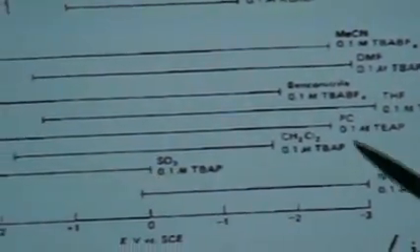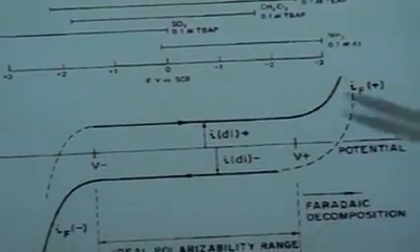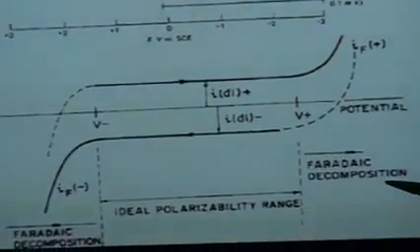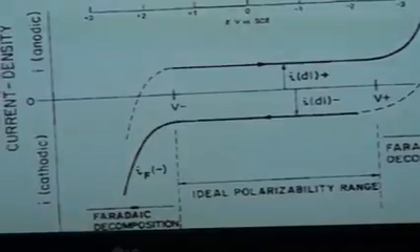Whereas if we move from aqueous to organic electrolytes, now what do you observe? That the electrochemical voltage window is increased. Okay, so when we have organic electrolytes, they undergo decomposition at a much higher voltage, so you have much broader voltage window. And when you have a CV curve, if you see a peaking of the current here, that means the electrolyte is undergoing a Faradaic decomposition. So this decides what voltage we should use, and electrolyte can be operated.